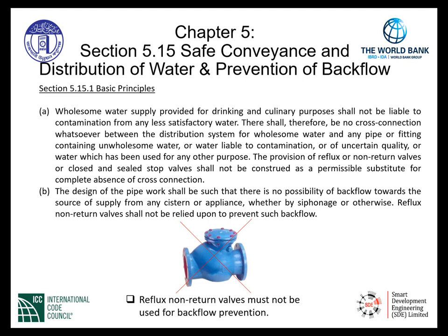There shall therefore be no cross connection whatsoever between the distribution system for wholesome water and any pipe or fitting containing unwholesome water. In other words, no cross connections are permitted, or water liable to contamination, or of uncertain quality, or water which has been used for any other purpose.